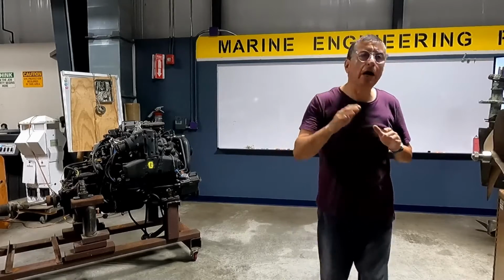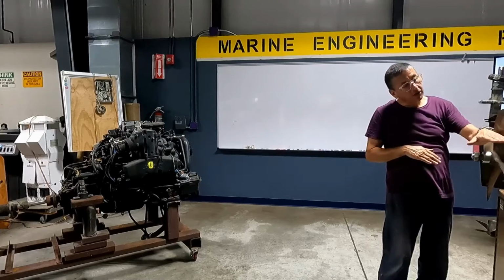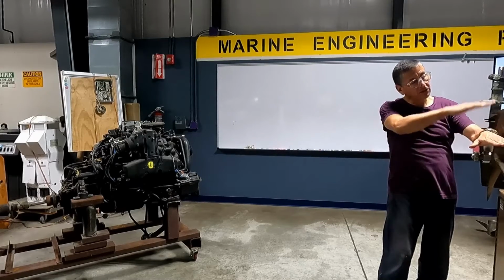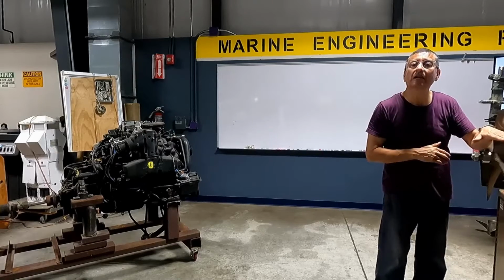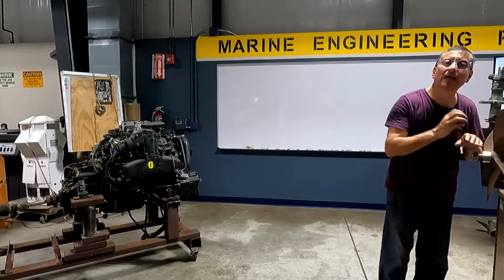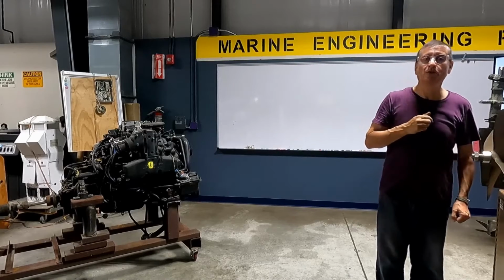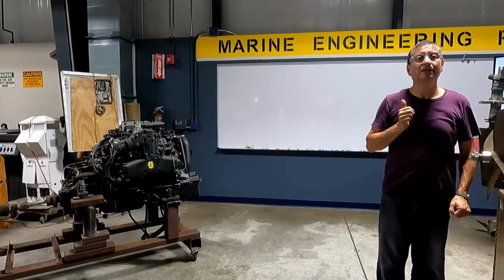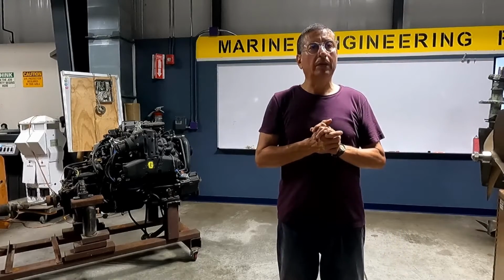And what happens when the propeller, this is the water line, is working in conditions like this, with some part of the propeller out of the water? Ventilation. It produces ventilation. And the symptom is similar, the blade of the propeller is eroded. But this is because of ventilation, not because of cavitation. Is that okay? Great. That's very important about the propeller.